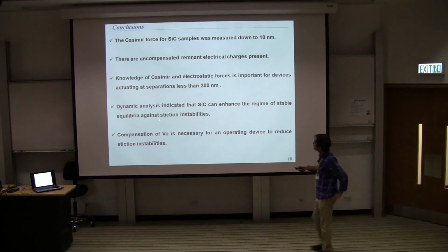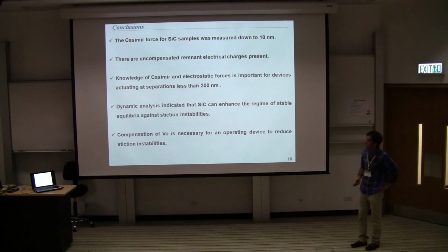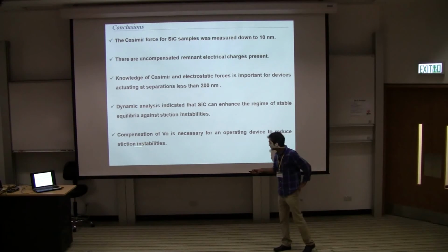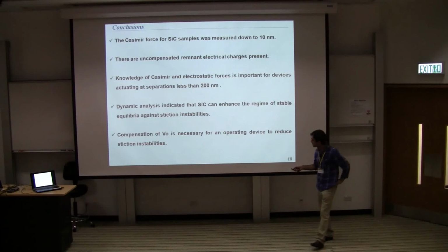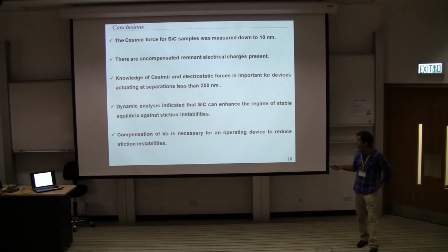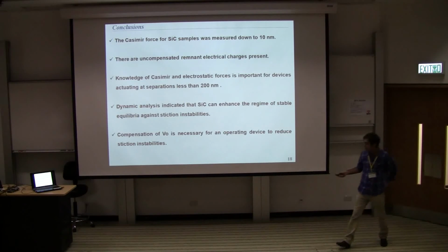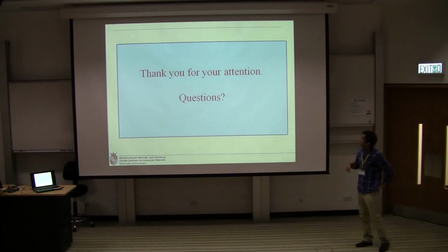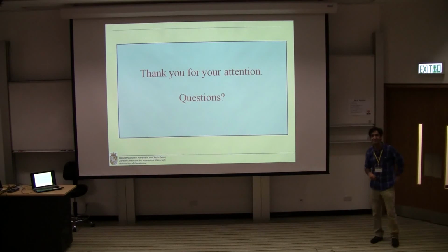We used dynamic analysis. It showed how silicon carbide can enhance the regime of stability against stiction. And we saw from the last slide that compensation of the contact potential is necessary for operating the device, to reduce stiction and improve stability. So that was my presentation. Questions?